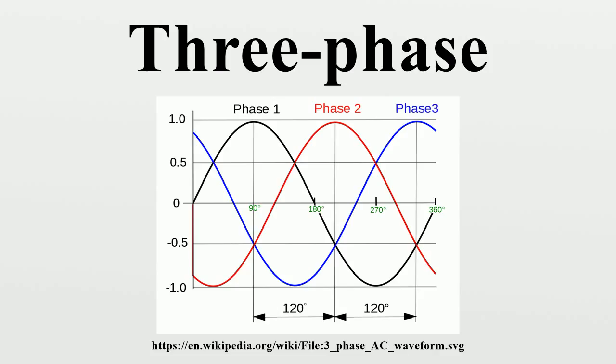System measurements. It is possible to measure the power in a three-phase system using two transducers when there is no neutral, or three transducers when there is neutral. Blondel's theorem states that the number of measurement elements required is one less than the number of current-carrying conductors.